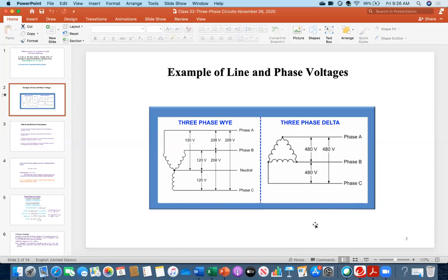But because they have grounding and your grounding is nearby, and if there is a good connection through the soil and it's a rainy day or it is wet, then from your grounding system, the current will enter into their grounding system and they will be affected. It also happens in real practice. So this means the issue is at your home, but that is causing the problem to your neighbor through the grounding.